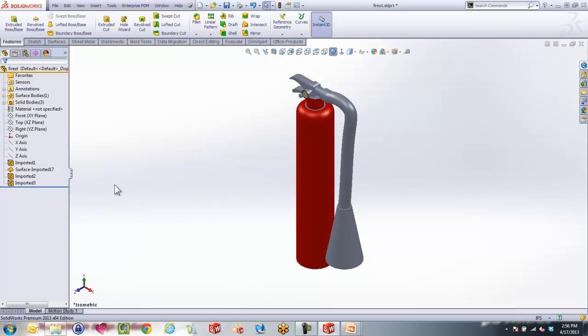There's another trick that many people don't know about, and that's called round tripping. That means that we took this part into SolidWorks, we fixed some of the things. Now, if we send it outside of SolidWorks using one of the neutral formats, such as IGES or STEP, and bring it back in again, they will actually try to repair the model too.